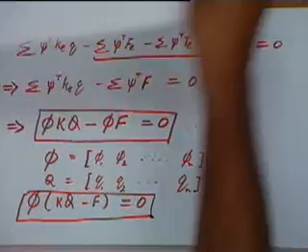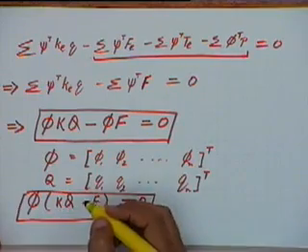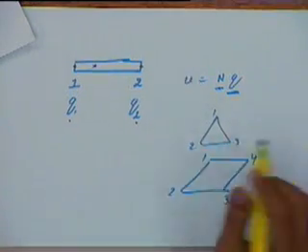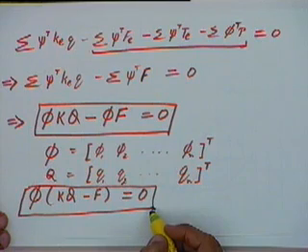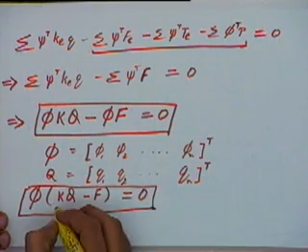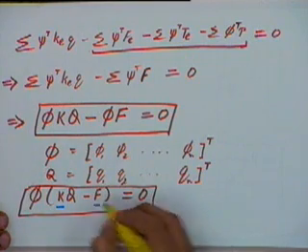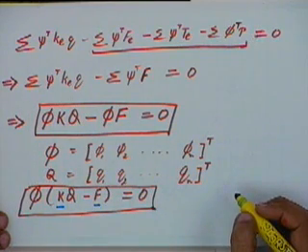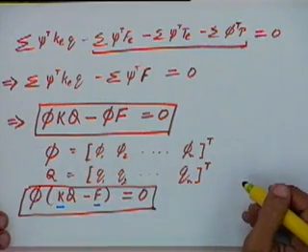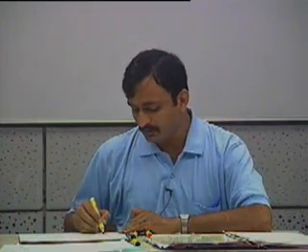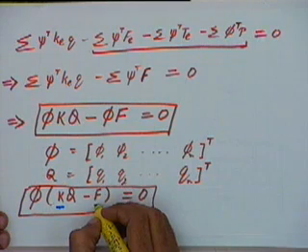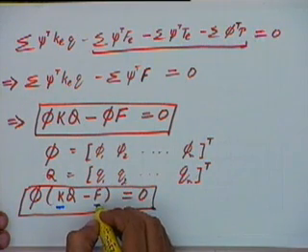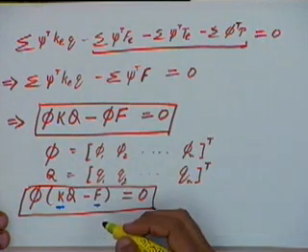So basically when we say that we will take a particular type of element, that is triangular or quadrilateral with 3 nodes, 4 nodes or 6 nodes or 10 nodes or whatever, we will finally come to the same set of equations. The only thing that will be different will be how to get K and how to get F. We will take different shape functions with every element and we will get different methods of assembling the K matrix and assembling the F matrix. But once the K and the F matrices have been assembled, the method of solution is going to remain the same.